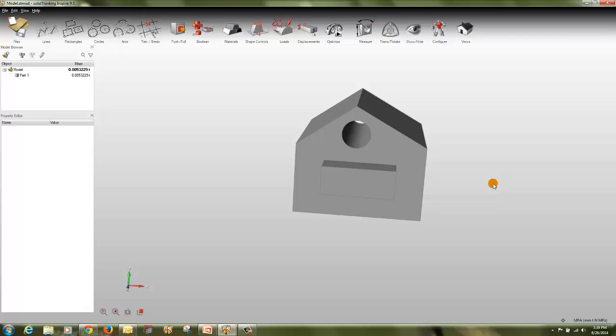Sketching tools are used to build or modify parts by drawing sketch curves. A curve is a wire entity such as a line, rectangle, circle or arc. Closed loops of curves automatically generate faces that can be pulled into solids when you exit sketching mode.